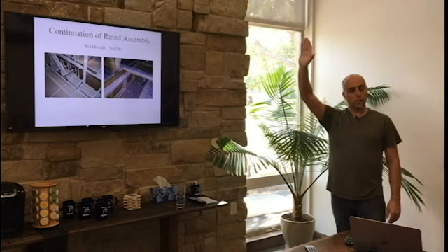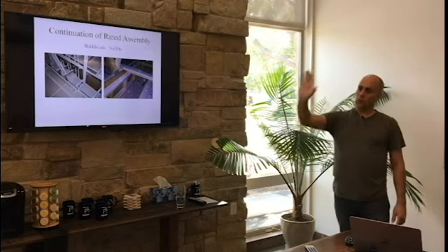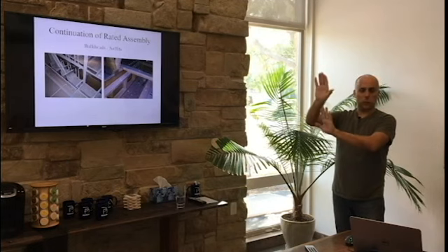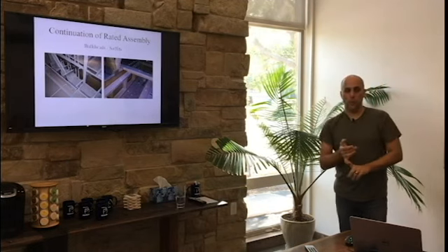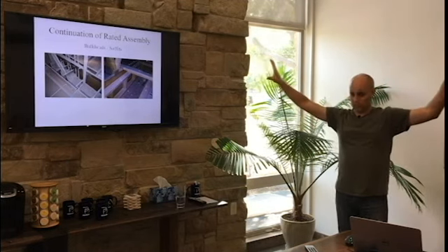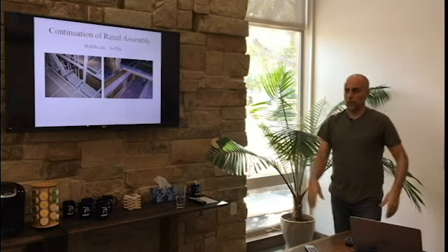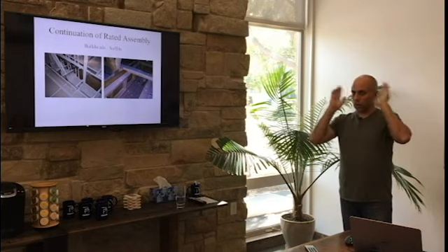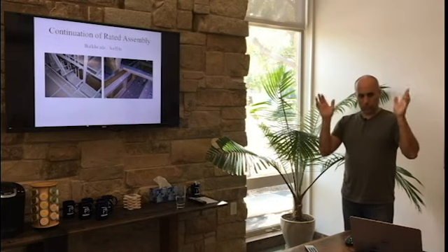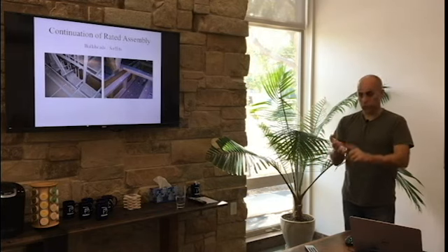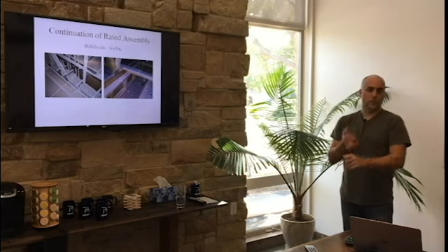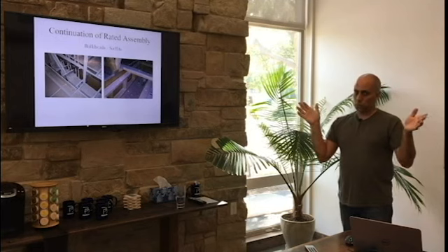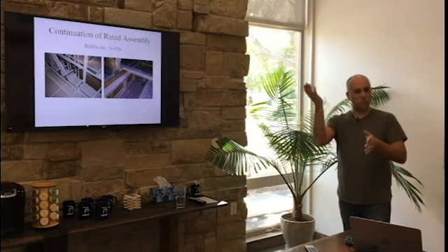One might have channels in one layer, one might just have one layer. Well, now I've got an issue because they stick out from each other. So you either have to plan for that ahead of time, or you're going to end up with this big band of 2 layers or a big band of channel with layer. But just because it changes orientation, people think wall, vertical, ceiling, horizontal. No. Is it roof structure or is it walls? Is it actually bearing wall? Because when the bearing wall stops, it's not wall anymore, now it's roof. Or it's roof ceiling assembly.